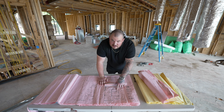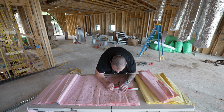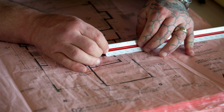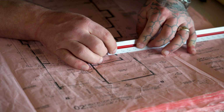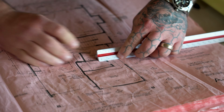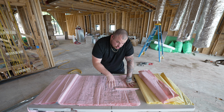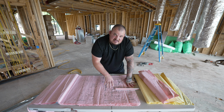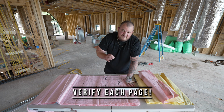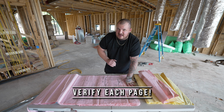There's a measurement right here. It says 3 foot 6 inches. So I come over with my scale, I verify. You start the 0 right at the beginning, and that's 1, 2, there's the line for 3, 3'6". Now I have verified that this drawing right here is to scale. Now each page is going to have multiple sets of different drawings. Verify every single one of them. I cannot stress to you how important that is.